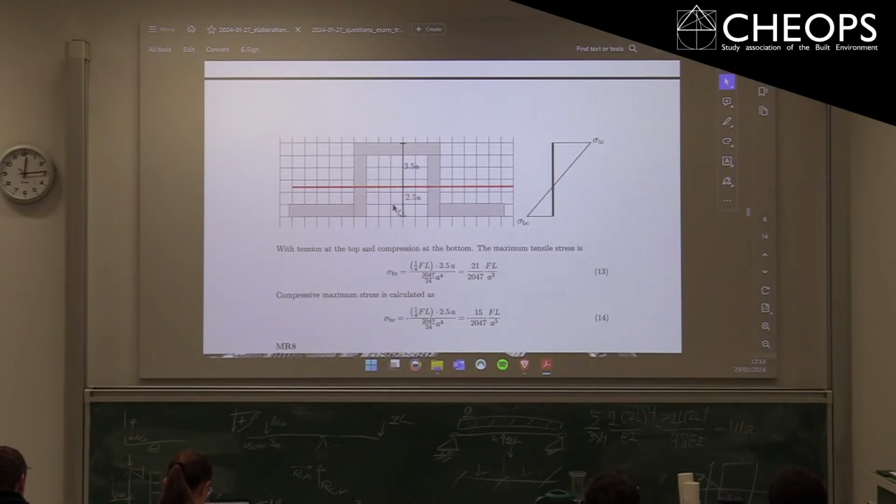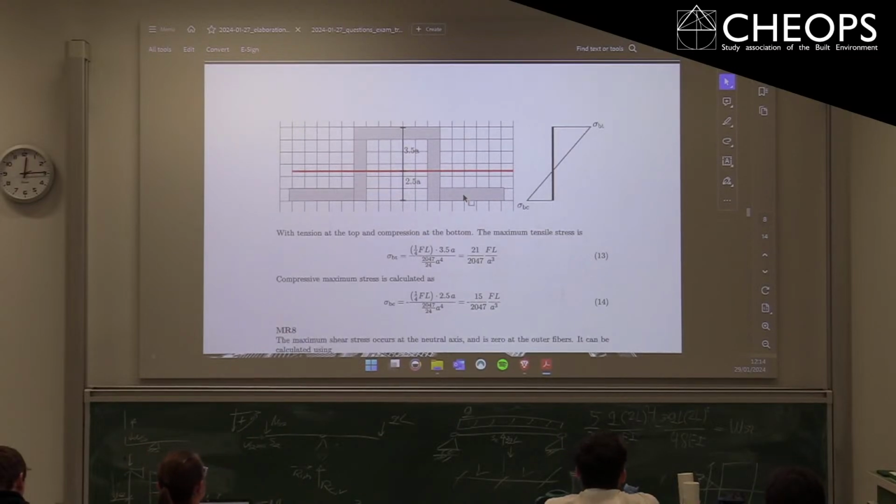So that is some notes on your bending moment diagram. These are different values. That's also perfectly fine. Tension and compression are also, well, stresses of a different nature. So be aware of these differences, and that you also have to, well, look at both sides if your cross-section is not symmetric vertically. And could you just repeat again how we know if it's this part?